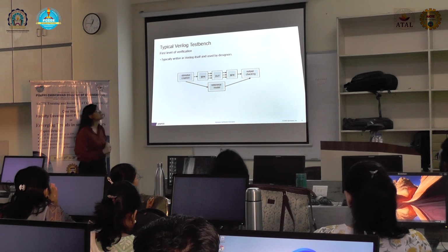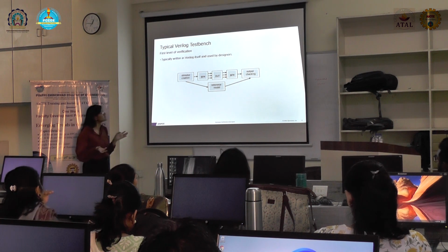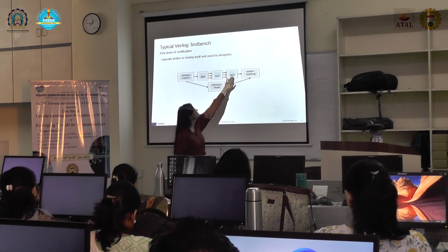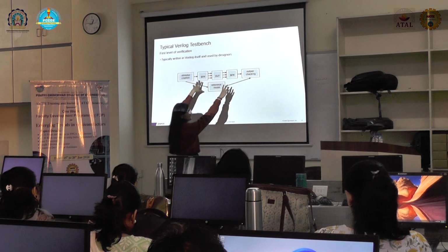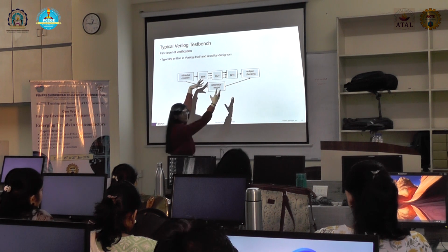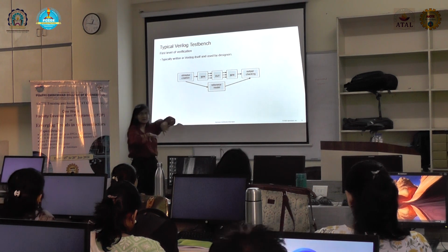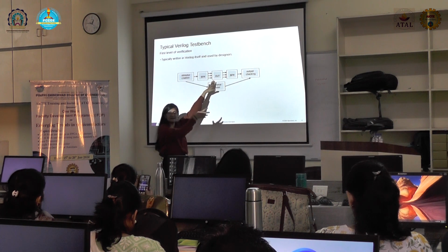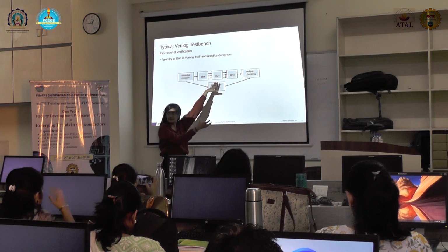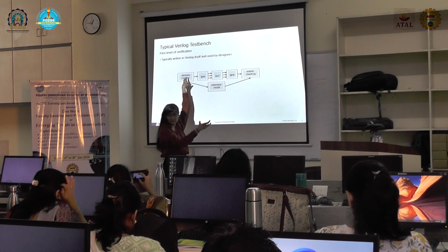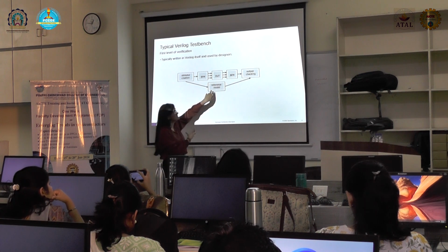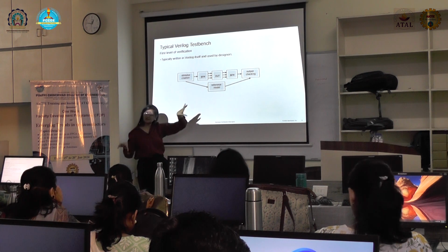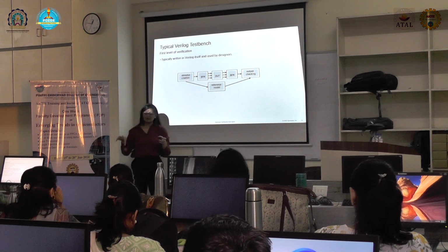So this is the typical structure of a Verilog testbench. We have the DUT, design under test. We have VIPs, which are nothing but the drivers or monitors which will drive data from the stimulus that we are generating onto the DUT, or collect the output data for the specific stimulus. As I mentioned, the reference model is the model in which we mimic the DUT functionality.